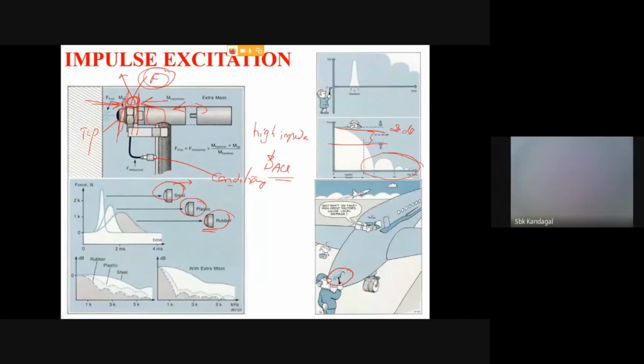Don't do the excitation too much, because it will not be able to excite the wing and the fuselage, etc. So it is better to use electrodynamic shakers, 4 electrodynamic shakers, one on the right wing, another on the left wing, in the front and the rear, because the energy needed by the hammer is so high that you may damage the aircraft.